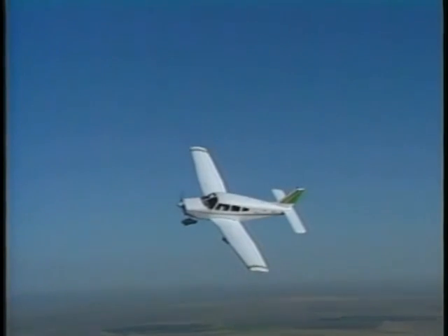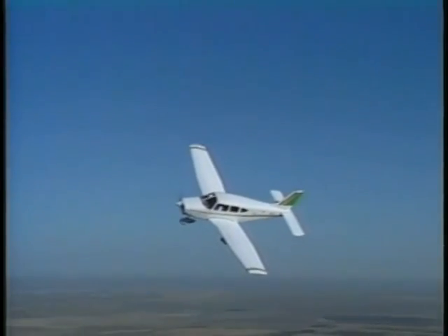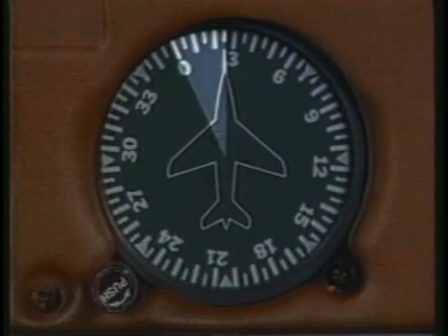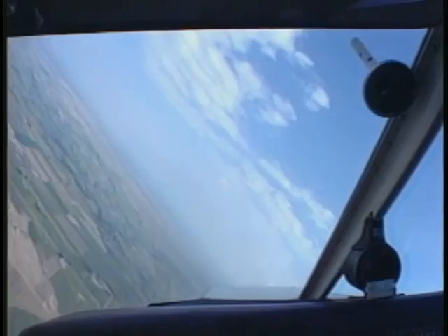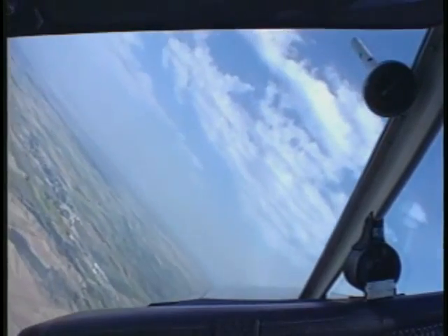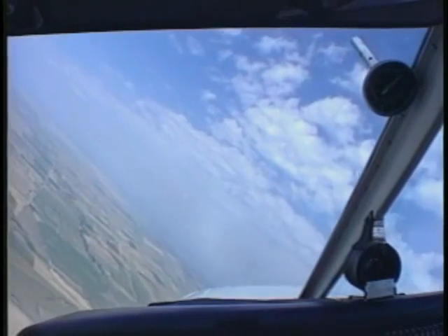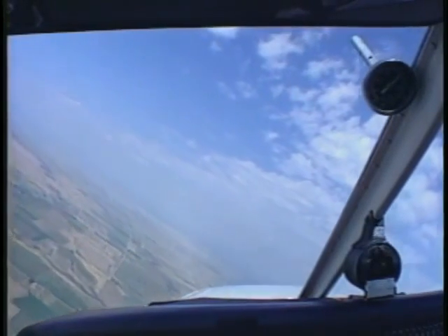The recovery from the turn should be as smooth and precise as the rest of the maneuver. Anticipate the rollout by applying the general rule of thumb of 1/2 your bank angle. In this situation, the rollout should begin approximately 25 degrees before the recovery heading. As you roll out of the turn, the load factor imposed on the airplane is reduced quickly. This means you must decrease both back pressure and power to maintain altitude.